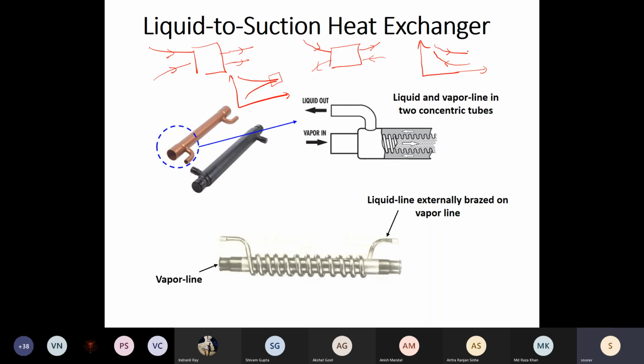And we can maintain almost similar amount of potential at both ends. In this case there is no inlet or exit, so at one end of the heat exchanger and the other end. So we can maintain more or less constant potential, or the change in potential between one end to the other end need not be as drastic as the parallel type configuration. Hence in the parallel type configuration, the hot fluid cannot go all the way till the coldest temperature of the cold fluid, and the cold fluid cannot go till the hottest temperature of the hot fluid.